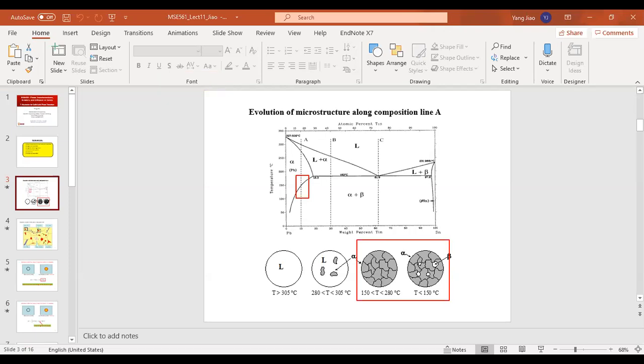If you think about what we have discussed up to this point, we talked about this regime in detail, the nucleation and growth regime, using the directional solidification of an alloy bar. In those cases, it's a one-dimensional system, which allows us to write down a lot of analytical results and obtain quite useful insights into the general process. So this is the normal nucleation and growth process.